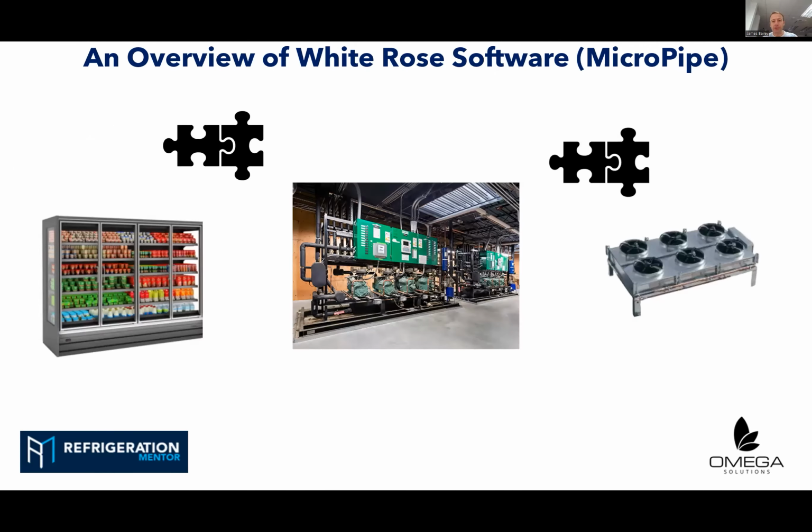So, talking the jigsaw theme, right in the middle, just an example rack. To the left, some showcases. To the right, condenser or gas cooler, depending on refrigerant. So it effectively sizes those lines between showcases and or cold room coolers with the rack, and then from the rack discharge header outlet to the condenser or gas cooler, and then those liquid drain lines back, before we send from the outlet of the liquid receiver back to the showcases.